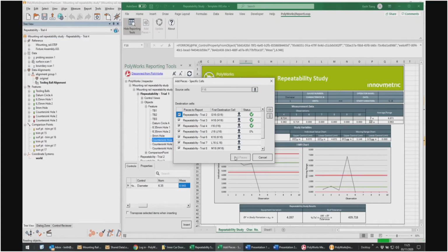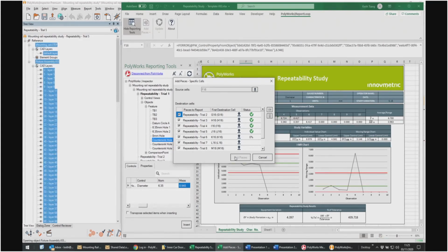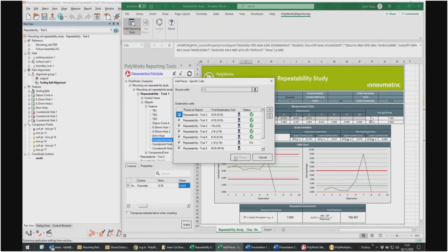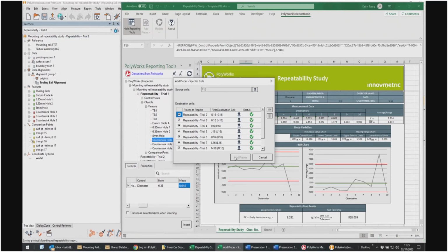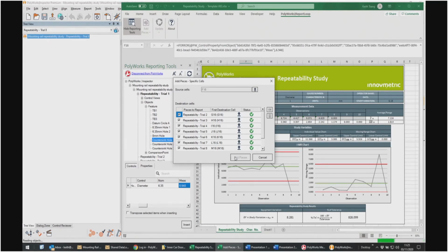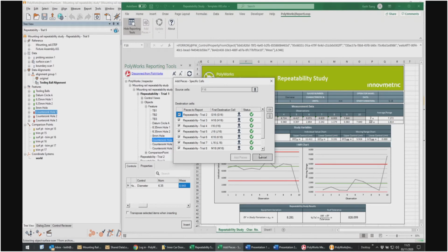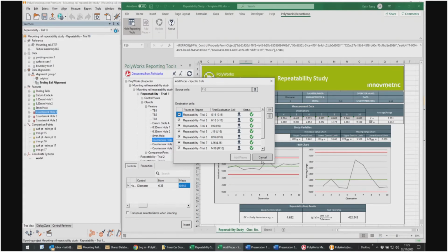What we want to see is a value of less than 30% of the tolerance used by the equipment variation. It also displays the values from the project on an IMR chart, or individual moving range chart. And that's about done there.